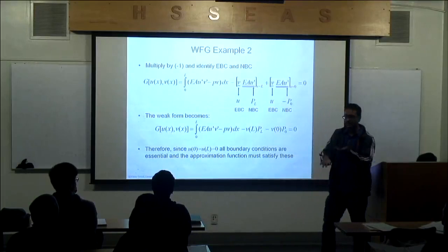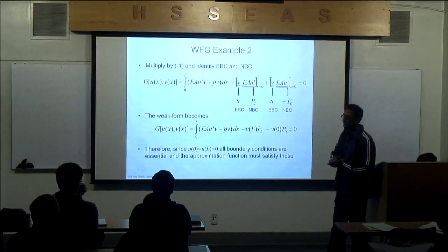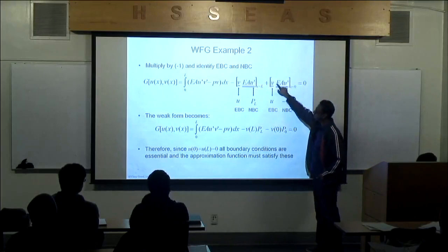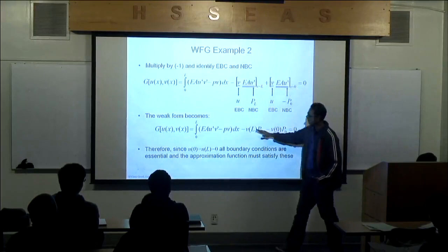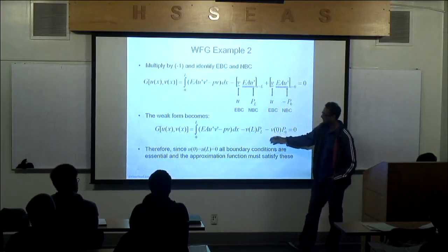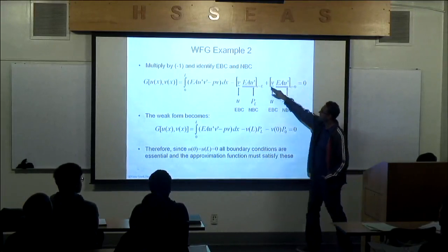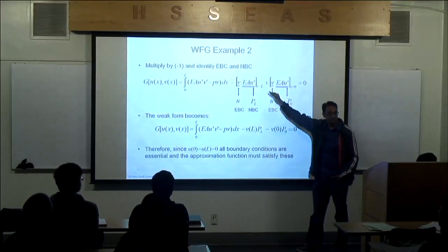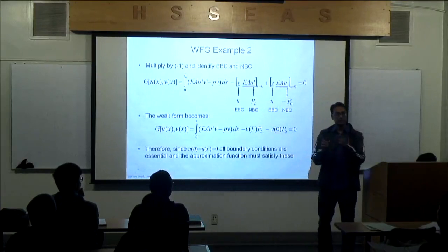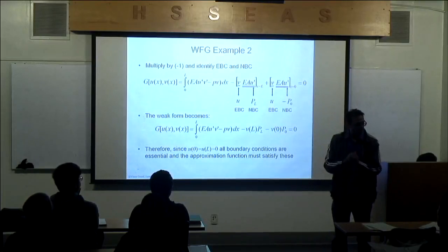It's incredible. When I first saw this, I said, how can this work out? But you will see on Thursday why it works out. Right now it's not clear why it works out, but it's okay. I'll show you. All right, and then here I have the boundary condition at x equals 0. So the weak form, and for convention I made a minus, so that both have the same sign, minus and minus. Okay, and then again, the weak form for this problem becomes this one here. You can still solve the problem with a plus here, and you can actually go and do all the calculations. It's going to work out. Don't worry about it. I made a minus to make the sign convention the same, so that when we derive the finite elements for a bar, we can use this approach.